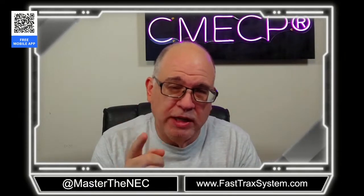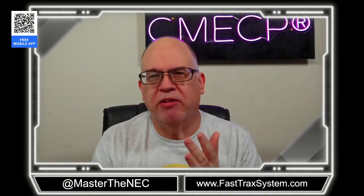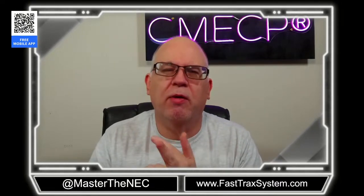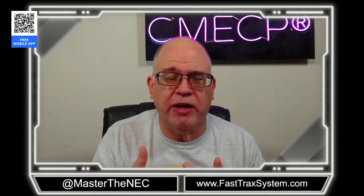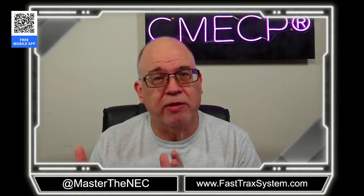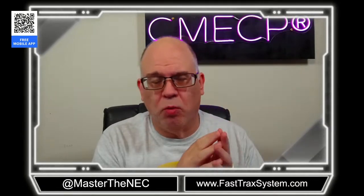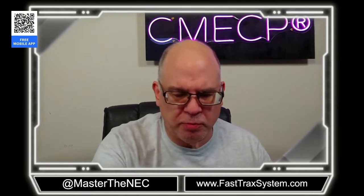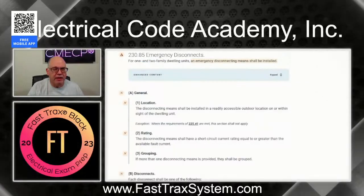Now, the 2023 edition of the NEC expanded a little bit, added a replacement requirement, added some marking requirements, and a little clarification. And if you have other energy sources to the building, like PV or a generator, and maybe their disconnect is somewhere else, not grouped with the emergency disconnect location, then you're going to have to put a placard or directory telling people where that is. So we're going to look at that. We want to make sure that we keep all those things in perspective. So let's go on and go to the National Electrical Code.